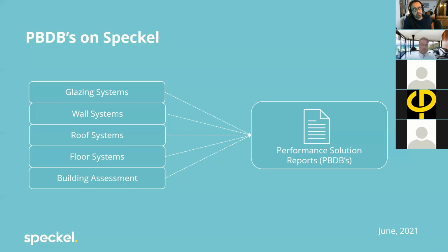And you'll see in the next version of the building assessment app that's about to come out that you can quickly just push, let's say you want to just create a mass, stack it, stick a 60% window to wall ratio across it.